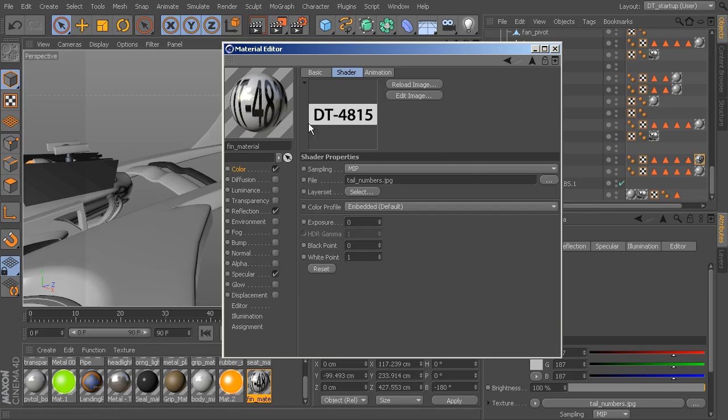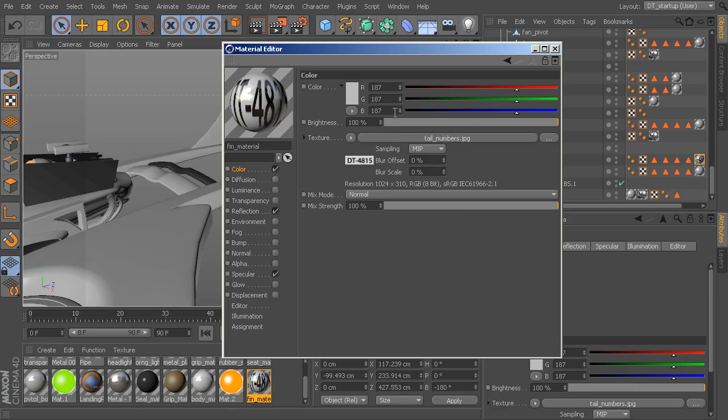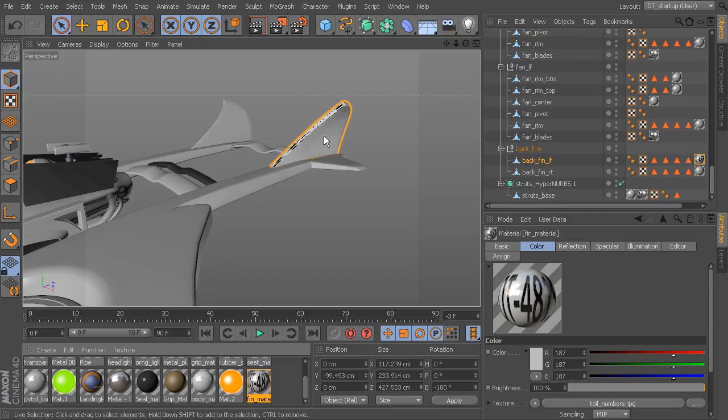Okay, your texture could be a square texture for a character. It could be a skin texture. It could be anything that you've created in another application, and now it's piped into the color. Now if we want to mix it with the color underneath, we can change this so that if our color here is red, you can see that it will blend it with the underlying color. We want to keep our color the same, so we'll say normal for that.